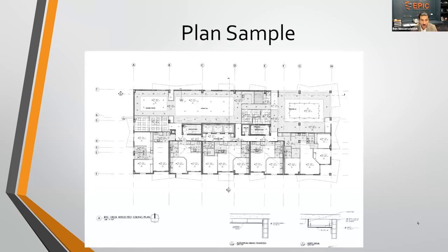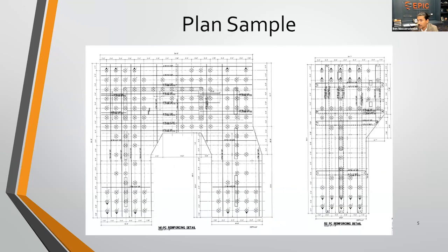And here's just an example of that site plan as I was talking about. So this is just going to be the overall floor plan, plain and simple. Well, this is showing a reflective ceiling plan, but the same thing would really apply. You obviously have some structural details as well. If you needed to have any structural design or any mechanical design, they would all be in their separate sections. So they have separate prefixes. A is going to be architectural, S is going to be structural, M or MEP, mechanical, E, electrical, P, plumbing, fire protection would be FP, and the list goes on.